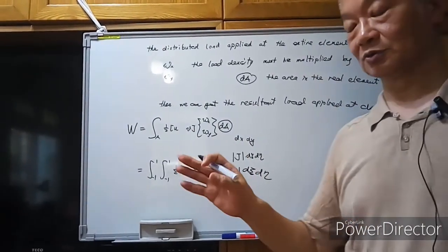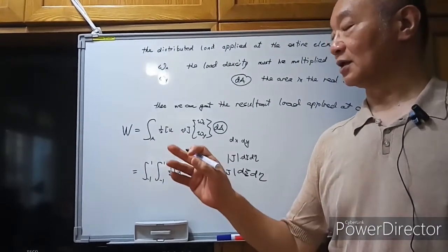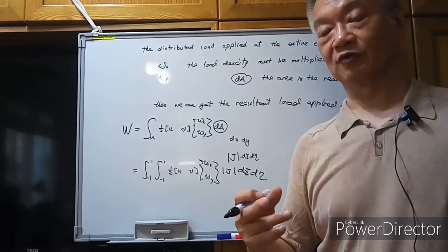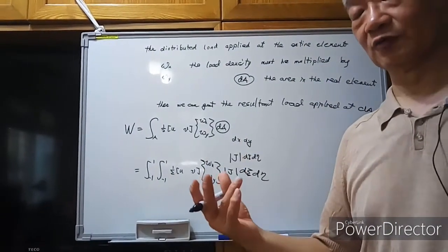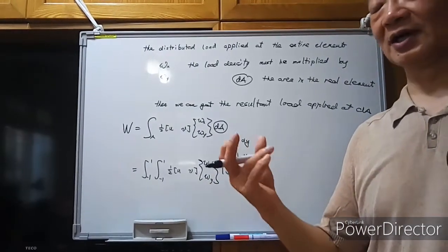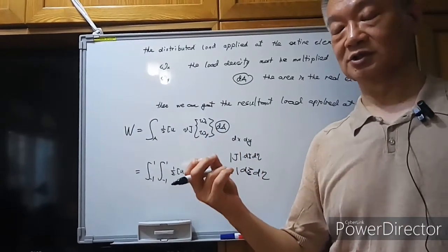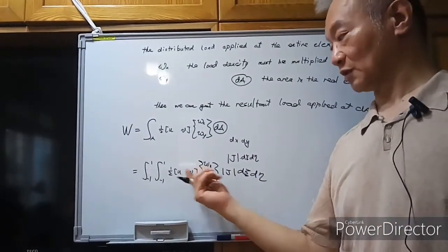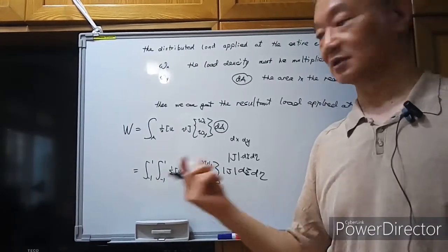Also, we need to use the shape functions. If we use a 4-node element, then there are 4 corresponding shape functions. We need to multiply the unknown nodal displacements by the corresponding shape functions. Then we can calculate the u and the v inside an element.